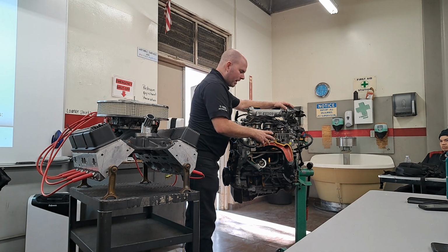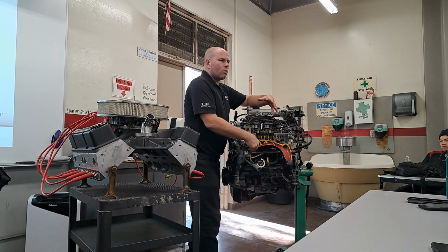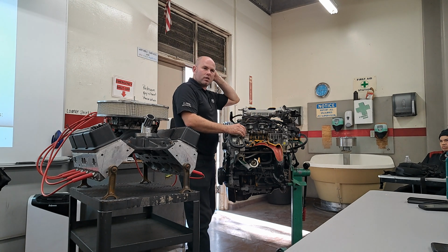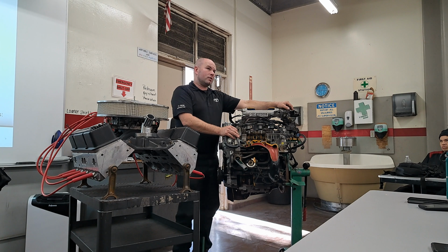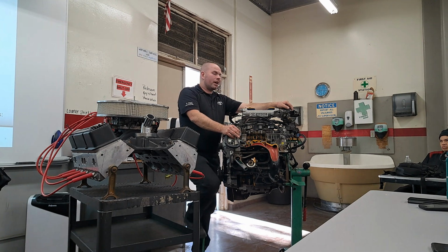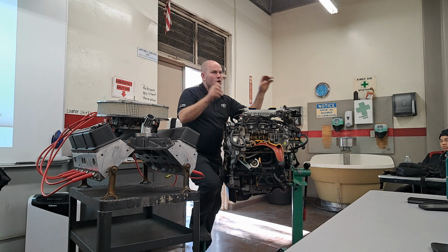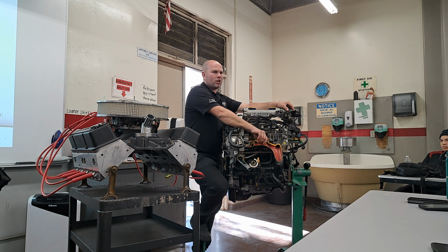So when it's a manifold, we start grouping the exhaust streams together quickly. With a header, we're going to keep them separate until we get down to a collector. So the header is really for performance. Some cars come with headers from the factory, like that Celica with the 2ZZ that I blew up. It was called a manifold, but if you looked at it, it was literally welded steel. It was a header, but they called it a manifold.